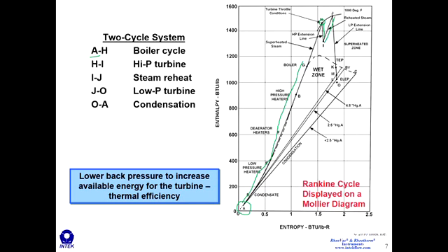We add energy back into the steam, and then that steam is driven down through the LP turbine. So again, the steam expands, it drops in temperature and pressure. We extract energy from that steam and create work. And so then the steam exits the turbine at a condition determined by the condenser. The condenser determines the pressure and temperature of the steam leaving the turbine.